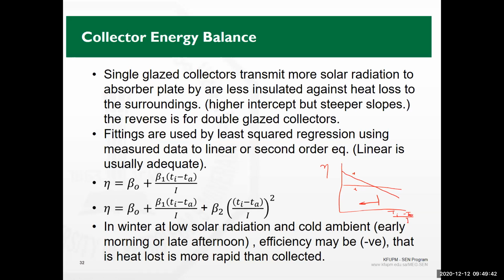That's why it's not a surprise when we did some sort of an extensive study for the utilization of solar collectors for water heating in the domestic sector. By the domestic sector, I mean hospitals and hotels. We did that study in the major cities of the kingdom, and it was not a surprise that all we got was a recommendation for a flat plate collector rather than an evacuated tube collector, because the water temperature is not very cold, even in winter, so we are always in this area. So the flat plate collector efficiency is higher than the evacuated tube collector, which is the double glass one.